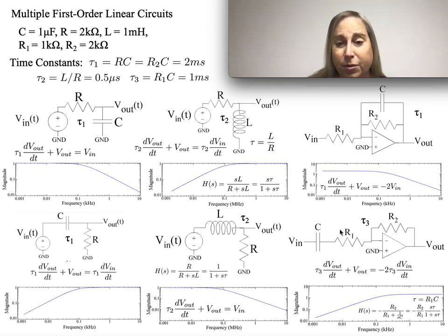If I look at the lower structure and I actually solve this out, what I would find is, yes, indeed, I get a gain of minus 2 at high frequencies. At low frequencies, it falls off because this capacitance now is in the resistance going into the amplifier, and effectively at low frequencies, this capacitance looks like a bigger and bigger resistance.